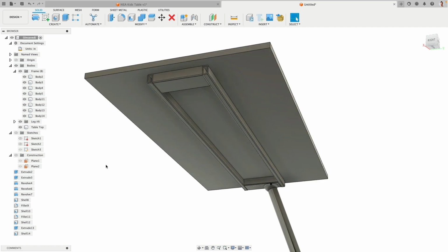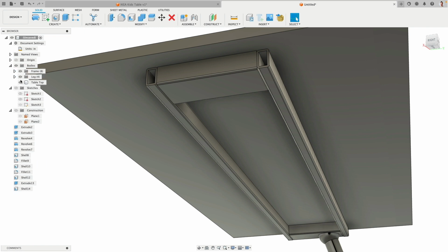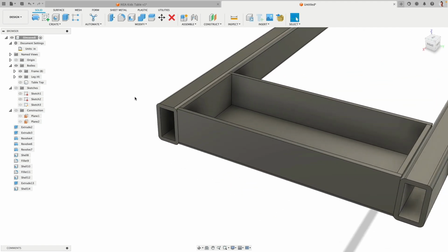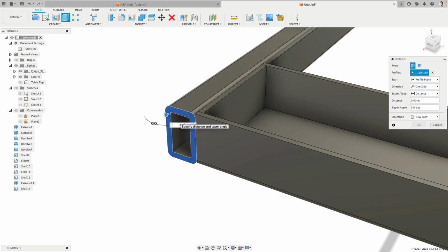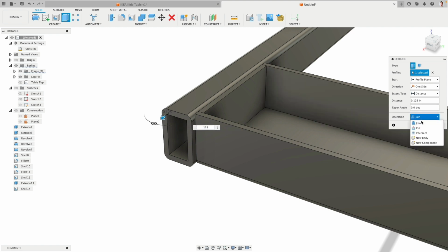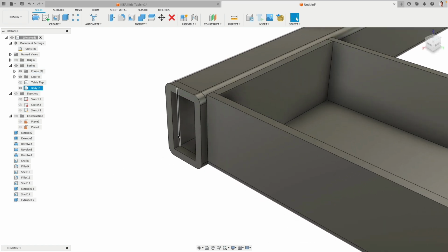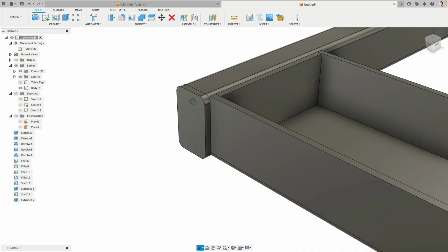Very good. So one thing left, there's actually an opening here. This is also a nice example of how we can do direct modeling. Really nice and fast. So I just would like to create a cap, something that sits on top. So I will extrude this face 0.25 of an inch, but as a new body. Very good. But then, yeah, I still have that hole. How do I get rid of that hole? Well, that's easy. We just simply select these internal faces and click delete.